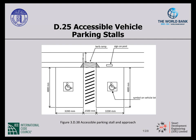The parking space should be a firm, non-slippery, leveled, solid surface, and you should have a sign posted at the entrance of the parking lot and at the parking space, and directional signage at every change in direction. The size and location of the posted signs should ensure clear visibility along the accessible route.